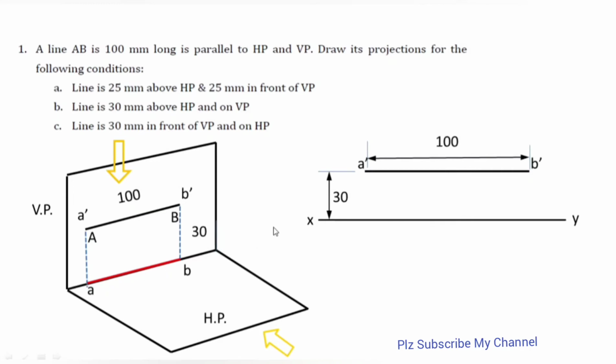How are we going to do it? With the help of a 2H pencil, I need to draw two perpendiculars, one in this direction and another in this direction, and we need to darken its top view also in this way, and its name is small a and small b. This is the required solution of problem B.